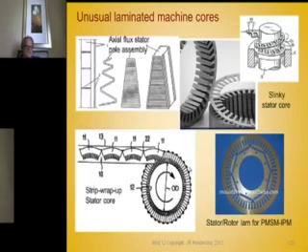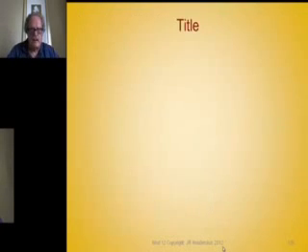With multiple teeth, you only do this with these hinges built in to build a core with very low iron losses. That's really the only purpose of doing this. If you play a trick like this with hinges and you have an individual tooth, then you can wind on them while you're in the linear state and then wrap it up later. And there are people who do that.